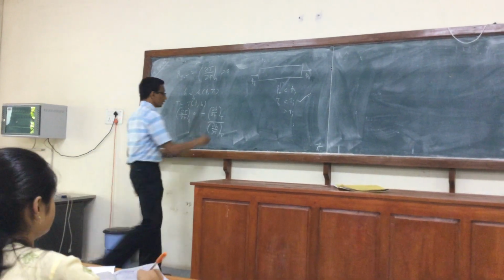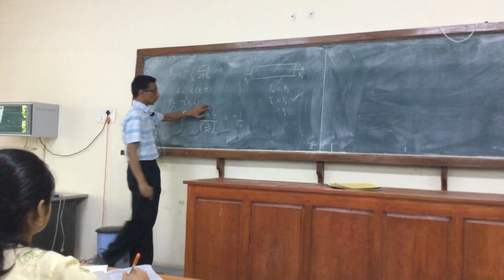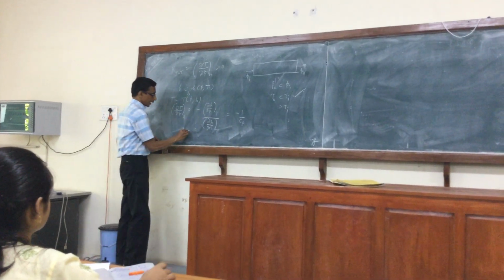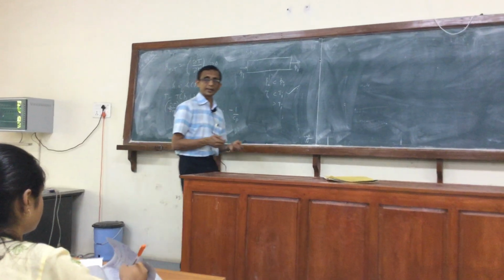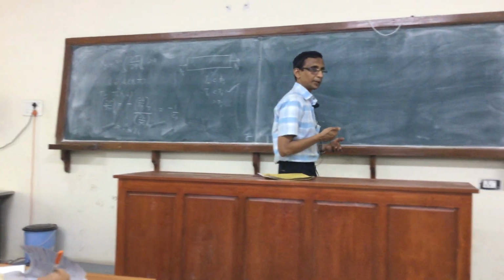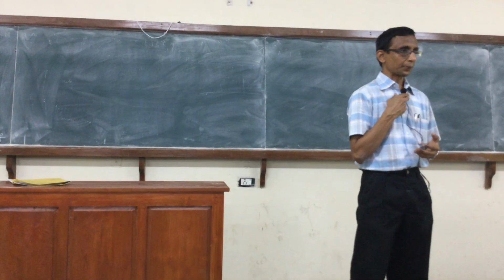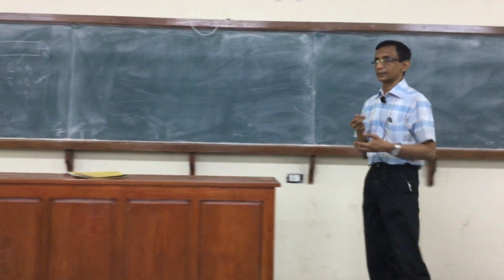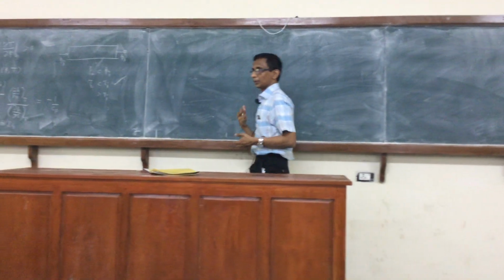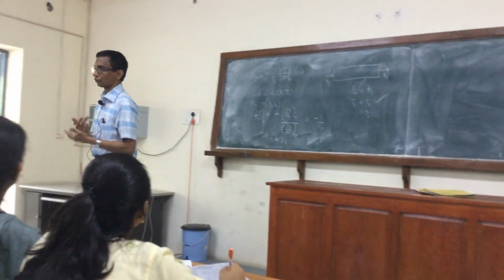over dH by dT at P. Right? So this is minus 1 over Cp times dH by dP, and just by looking at this you can see this is actually 0 for an ideal gas, because we know that for an ideal gas, dH by dP is 0. The enthalpy doesn't depend on the pressure. In an ideal gas, what it means is that whatever may be the degree of expansion, temperature will not change.